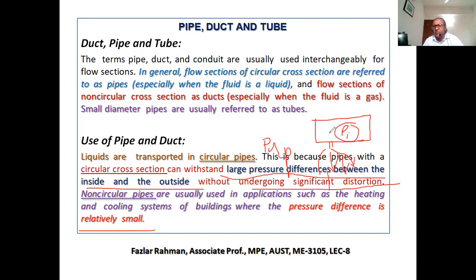But this increase of pressure in the upstream will give you more air to flow down smoothly. But this pressure difference, obviously, is not that much. Say atmospheric pressure is 14.7 psi, right? So right inside, you need to maintain like 16 or 16.5, around 17 psi.